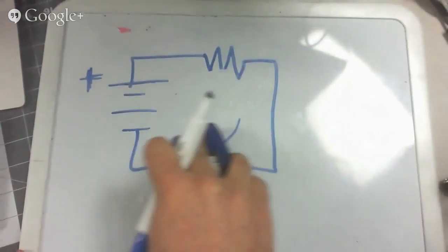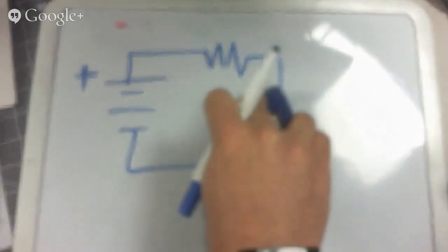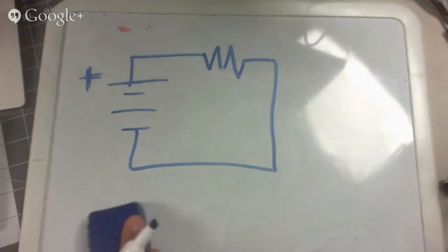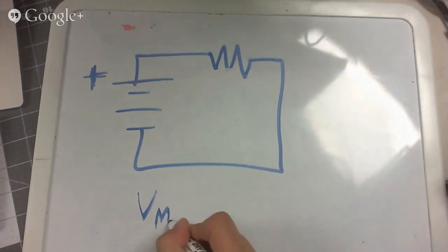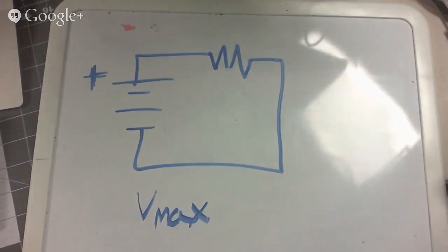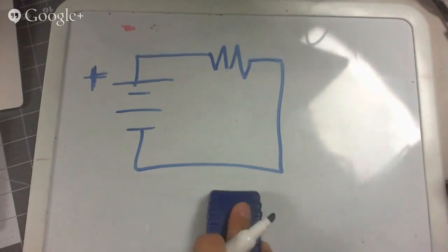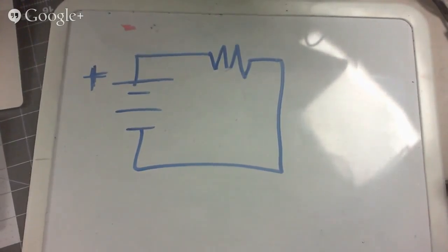The other thing, we're going to kind of bring this together now. When you're doing electronics, before we get to the resistor, your parts are going to be spec'd in a voltage, sometimes Vmax, and then a max current, a forward current.